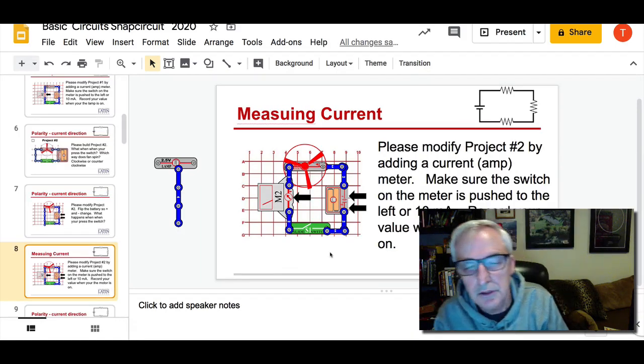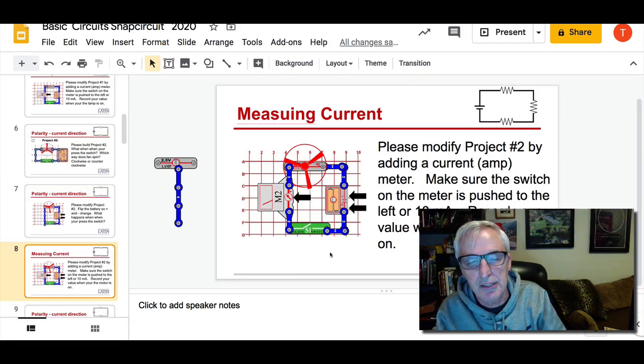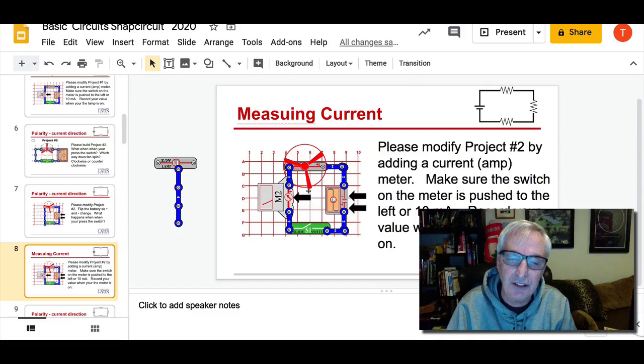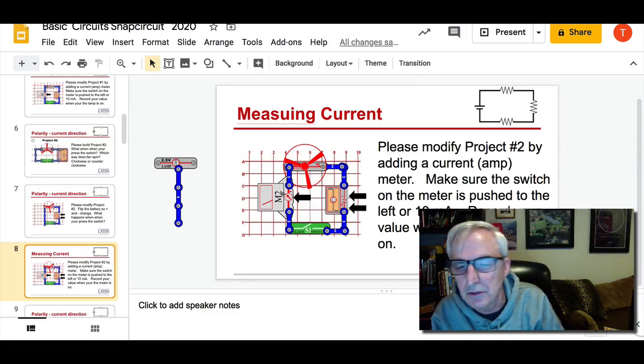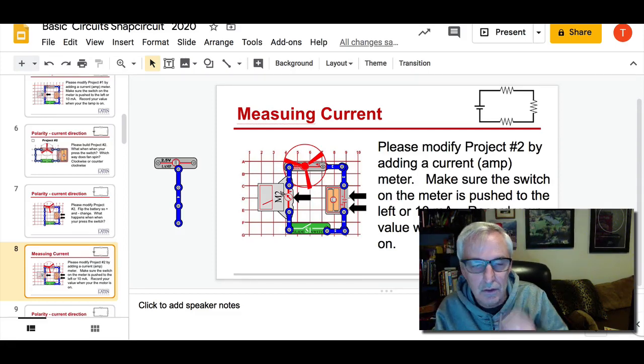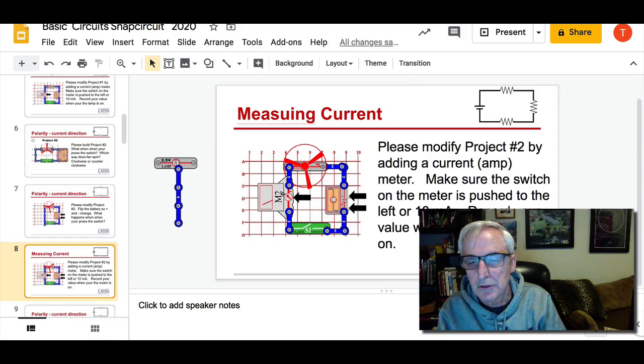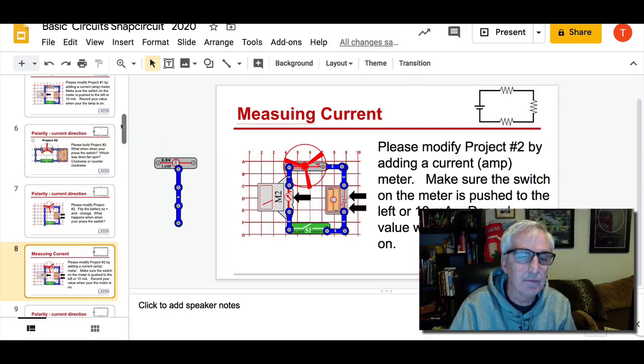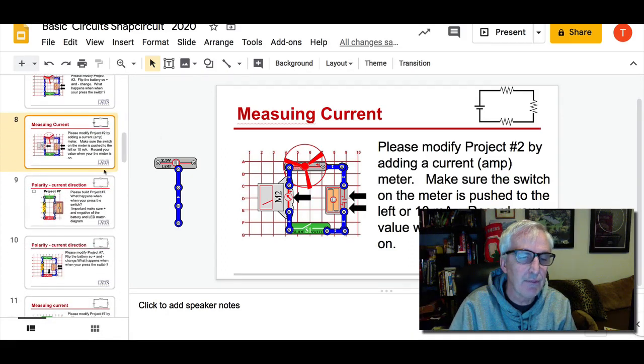Next thing. You've done that. You've tested it. Hopefully you've switched it. Next thing, put the meter on there. Turn the fan on. See what the meter does. All right. Record that on the handout I gave you, because that's what I want to receive back from you.